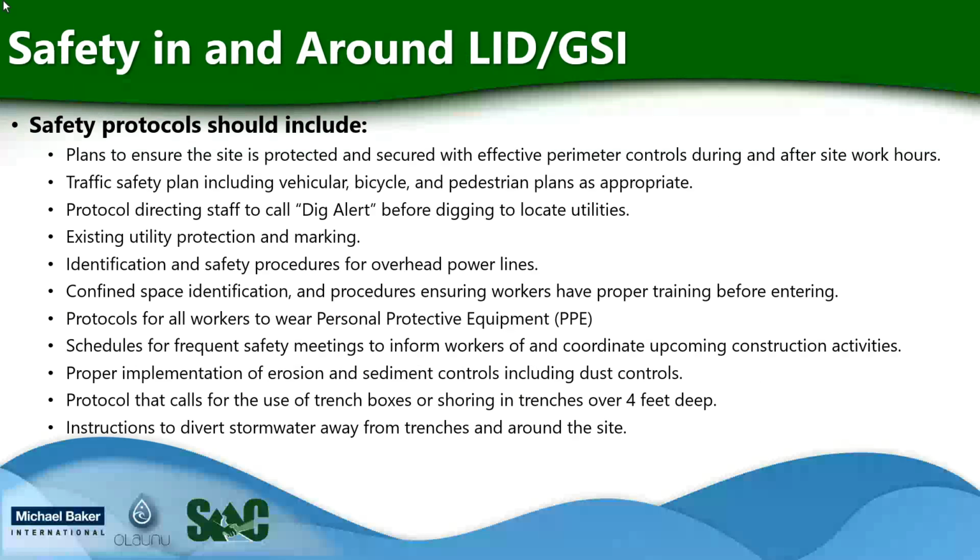There should be a traffic safety plan that includes vehicle, bicycle, and pedestrian plans. There should also be protocols directing staff to call Dig Alert before digging to locate utilities. Existing utility protection and marking. There should be identification of safety procedures for overhead power lines.